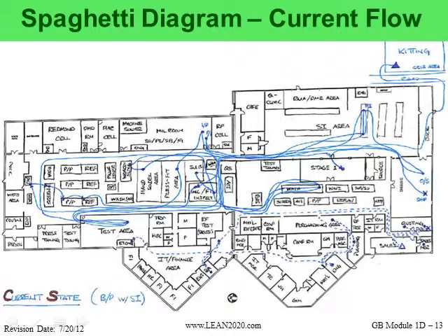So what can we do to do things a little bit better here? We actually want to spread our processes out in some aspects, but the operations that should be next to each other, we want to place next to each other. So we'll take some of the operations out, almost like a domino effect here. We're going to remove some, slide some others in place, and create a workflow that will allow us to have departments that pass product to each other, next to each other.